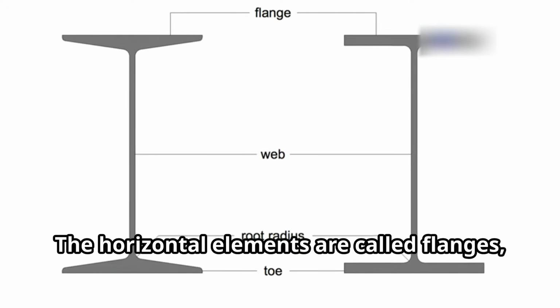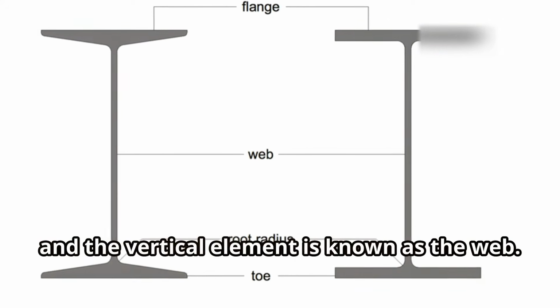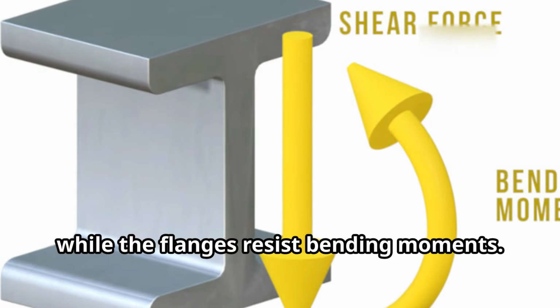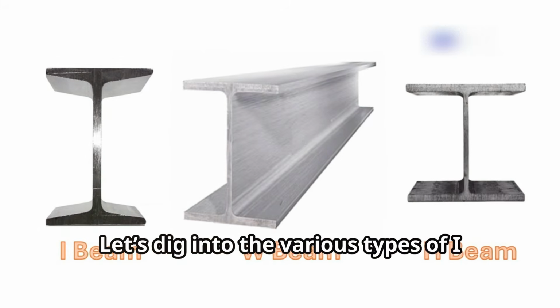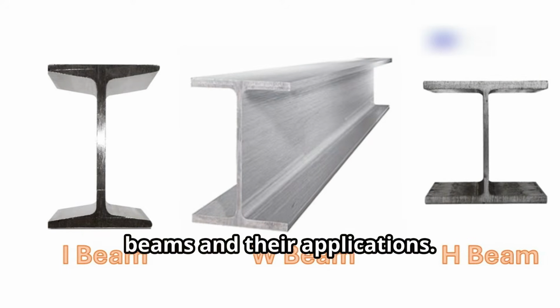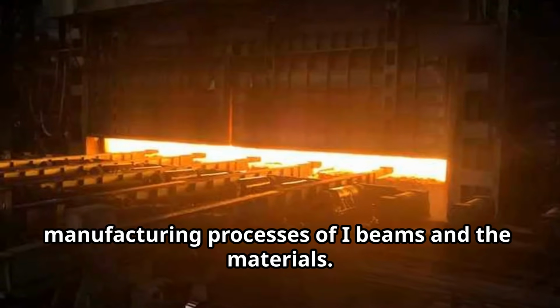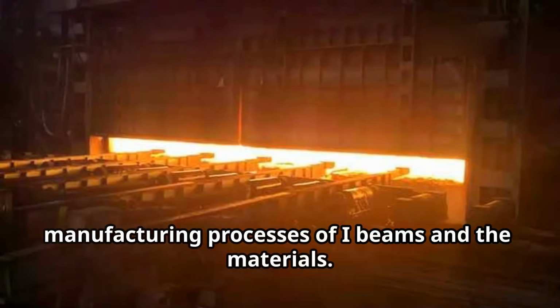The horizontal elements are called flanges and the vertical element is known as the web. The web resists shear forces while the flanges resist bending moments. Let's dig into the various types of I-beams and their applications. We'll also glance through the manufacturing processes of I-beams and the materials.